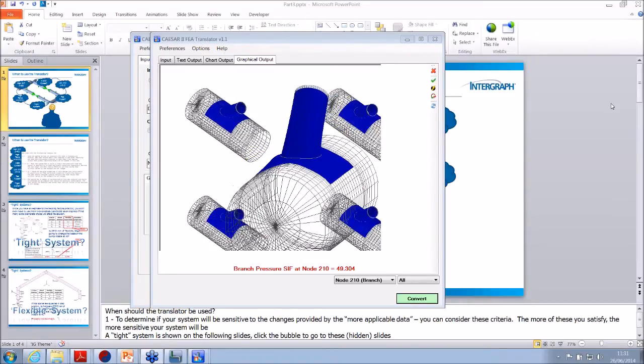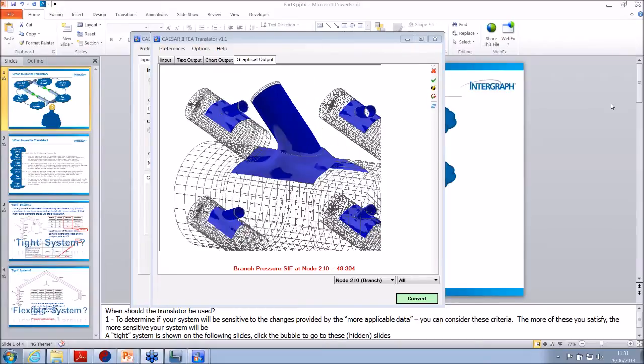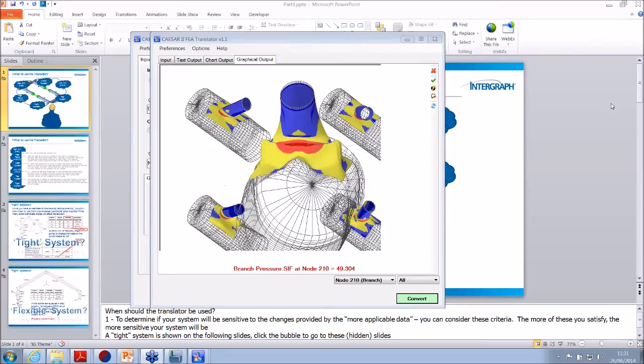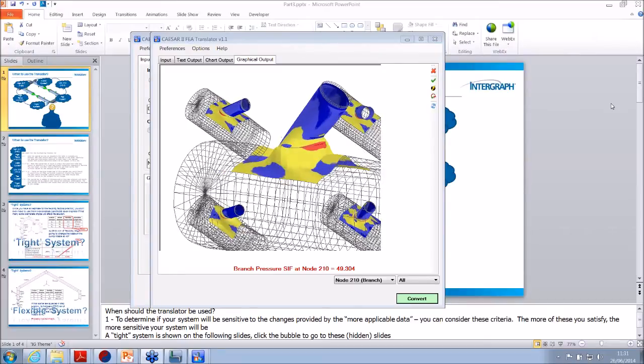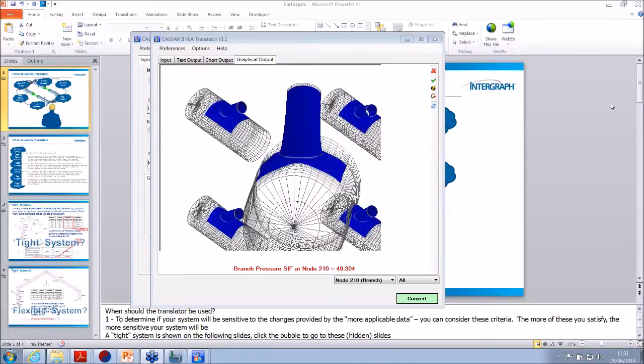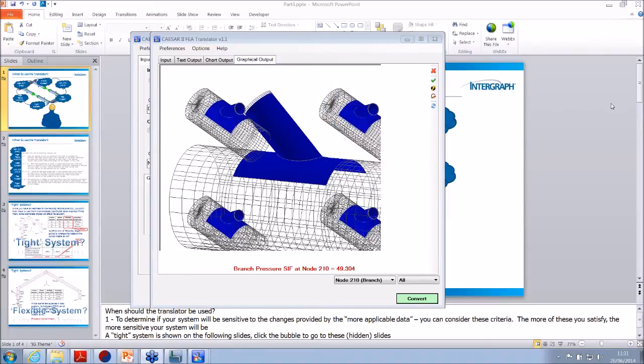Okay. And if the SIFs calculated by FEA tools are greater than B31.3, is it allowed to continue using values from B31.3? In other words, is it allowed to use mixed values from B31.3 and FEA tools? No, you can't really mix and match to see what suits you.